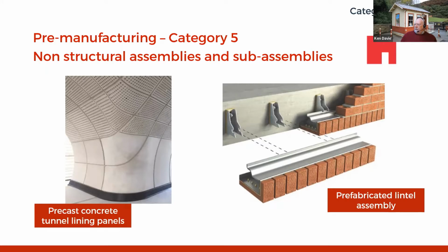The prefabricated lintel assembly is from IG, and it's designed such that it clips onto a concrete structure or a background structure. Interestingly, when I've actually seen those being used, the bricklayers were turning them upside down and pointing them while they were on a bench, which eliminates the need for them to lie on their backs on scaffolding and try to point upside down. So there's obviously a health and safety issue. Big advantage in actually eliminating potential risk and potential workplace injuries.